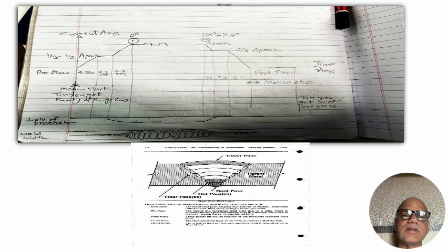And since we had the two options, either to stop the motion at this point where the downslope is starting, or we can stop the motion at this point where the post-flow is going to start. But for sensitive alloys like titanium and aluminum, it is good to stop motion here, so that you will get purging or the argon atmosphere continuously, or the CO2 atmosphere continuously across the weld or near the crater, and you don't have the oxidation of those areas.